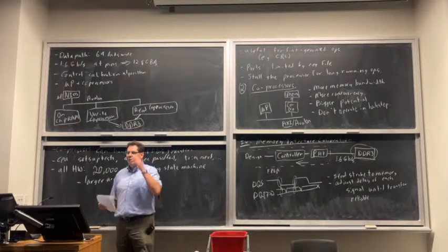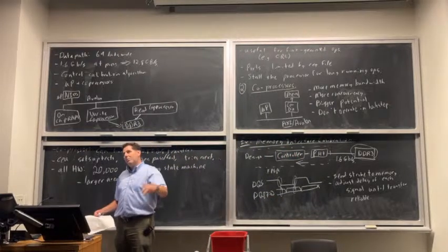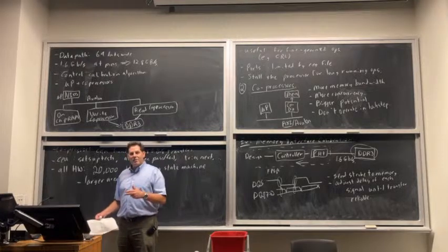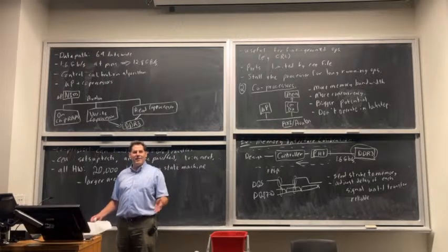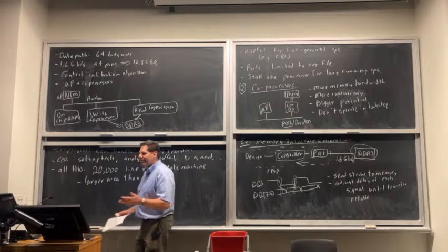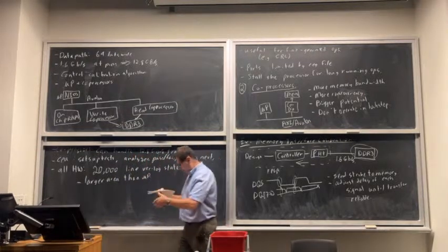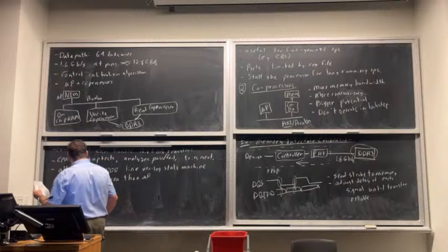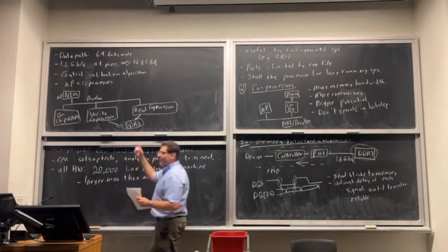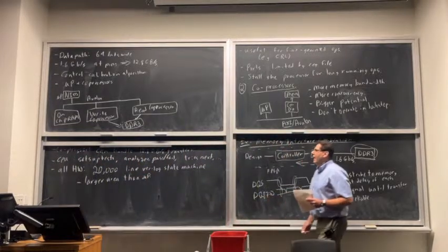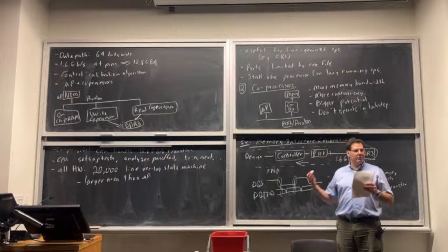It was so complicated, it was also becoming limiting in clock frequency, because you can imagine it's got all sorts of loops in it, right? It's actually hard to pipeline. So it's difficult to keep fast, and it's also very hard to maintain. You can imagine how nasty that is. So yeah, this is an example where it's worked very well. And it was an example also where a soft processor was good.